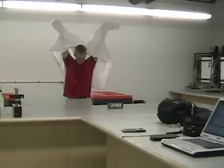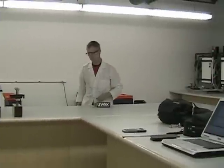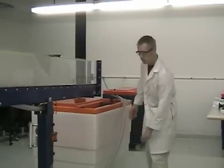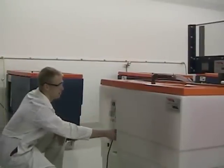Protective clothing is a good idea, but not required for this exercise. Before we start the flume, the hoses must be checked for loose connections to prevent leakage. You can now start the pump and set the flow rate.